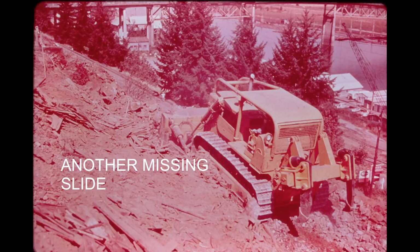The small dozers, TD7C and 8C, as well as their loader counterparts, the 100C and 125C, use a solid one-piece sprocket. And again, as on the medium-sized machines, the sprocket is easily removed because the track frame is mounted forward of the sprocket. The teeth at the bottom left of the sprocket are covered by the rock deflector.